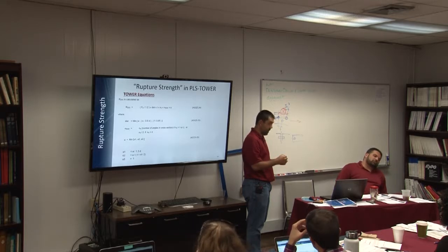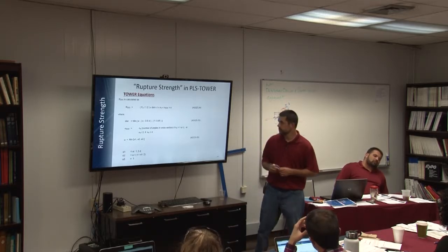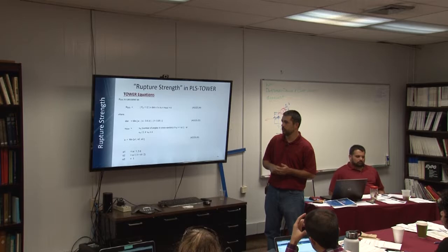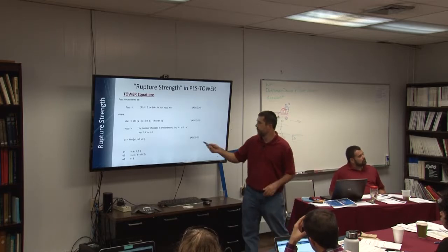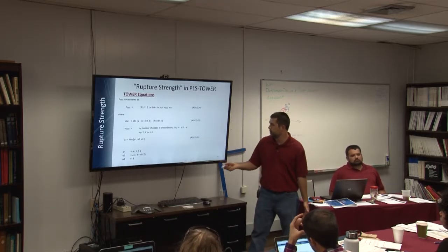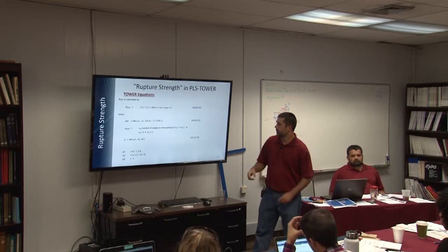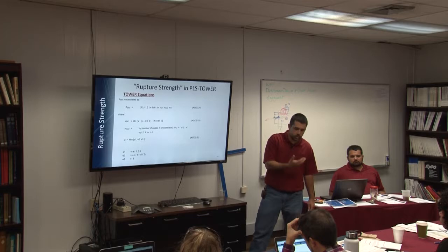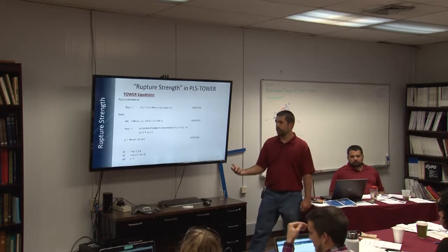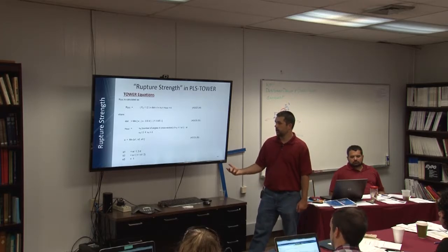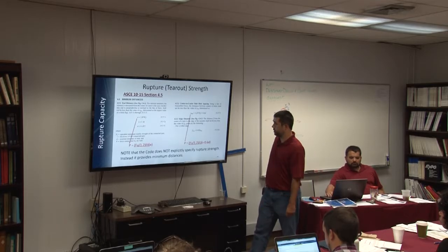You're just spreading a load over two angles. So in 99% of the cases, you're dealing with single angles, so the number of bearing areas is 1. Okay. Right? The last thing they do is, how do you handle the fact that, can you go down one more?